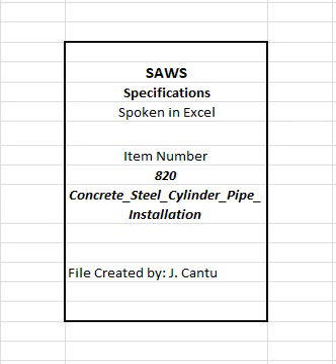820.3 Submittals. Contractor shall submit manufacturer's product data, instructions, recommendations, shop drawings, and certifications. 1. Submit shop drawings and certifications signed and sealed by a professional engineer registered in the state of Texas showing the following. 2. Manufacturer's pipe design and thrust restraint calculations in accordance with AWWA M9, latest edition. 3.